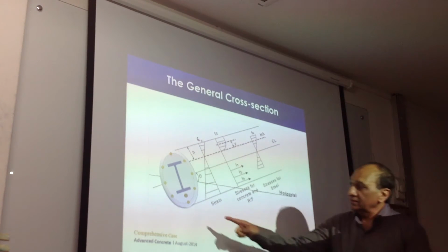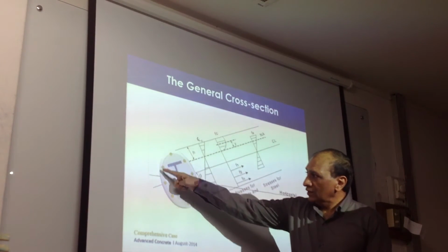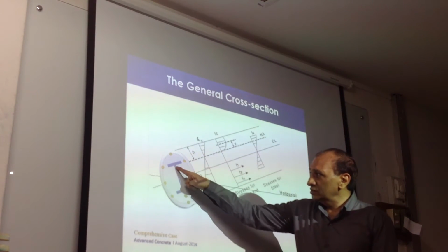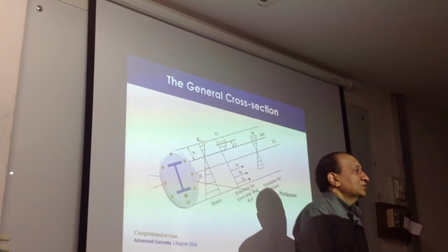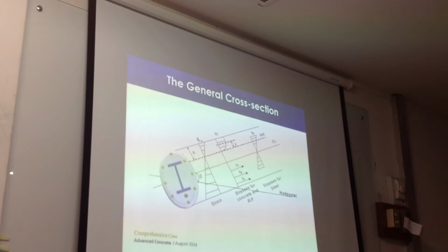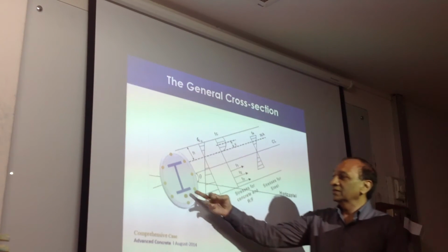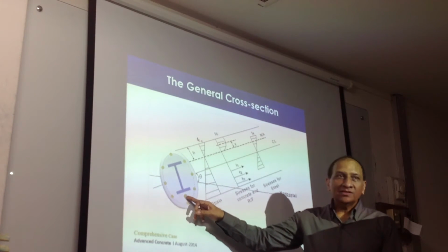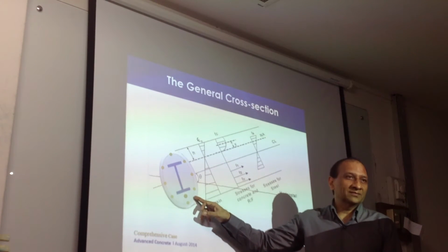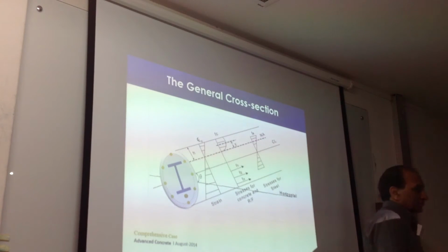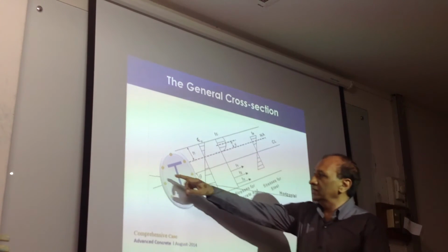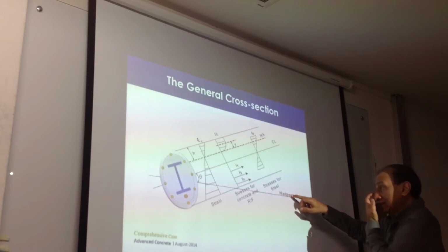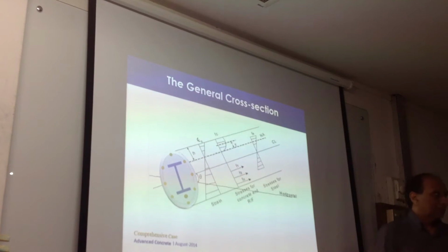First of all, let's consider a cross section of any shape which has a steel shape, concrete with steel inside, with rebars, and also a pre-stressing strand. Obviously, this may not be a real cross section, doesn't matter. But we're just saying that there's a cross section which has many materials: a steel section, a pre-stressing, a reinforcement, and concrete. It's a cross section, right? And we say that this is the normal direction of the horizontal, any arbitrary axis, right?